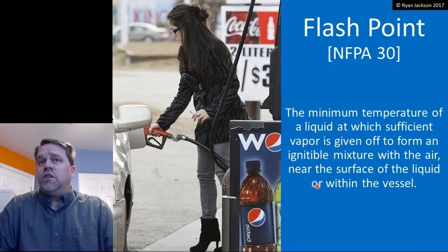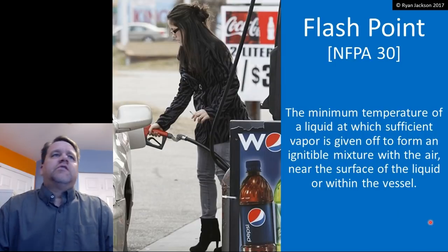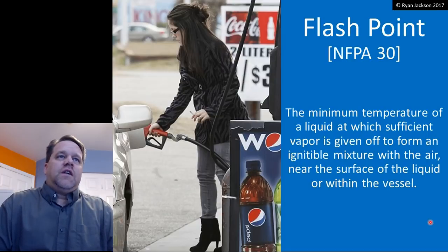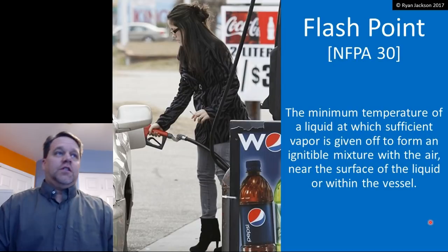The next definition is flash point. Flash point is defined in NFPA 30 and some others. It's the minimum temperature of a liquid at which sufficient vapor is given off to form an ignitable mixture with the air near the surface of the liquid or within the vessel. All right.